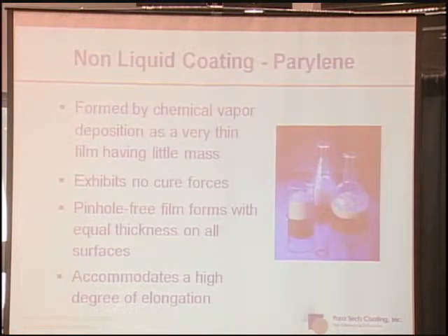A non-liquid coating material is Parylene, and I'm sure a number of you know about this material. It's formed by chemical vapor deposition, and it's put down in a very thin film having little mass. So that's one of the big advantages of it. It exhibits no cure forces, so your parts don't see any stress during the process. It's pinhole-free and forms with equal thickness on all surfaces.